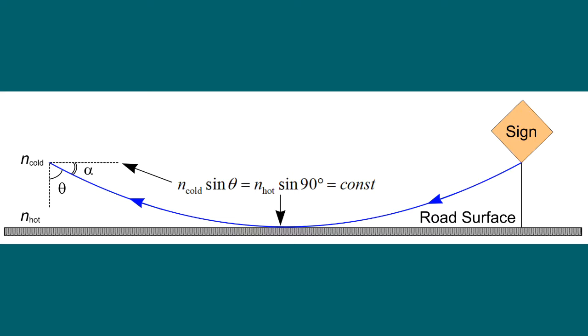road surface, which value we find from engineers who study asphalt surface temperatures given the ambient weather temperature. Then the refractive index of air can be calculated in each case based on the temperature. Plugging in the values, you can solve for the angle theta and then find its complementary angle alpha. The calculated value is essentially the same as that found earlier.